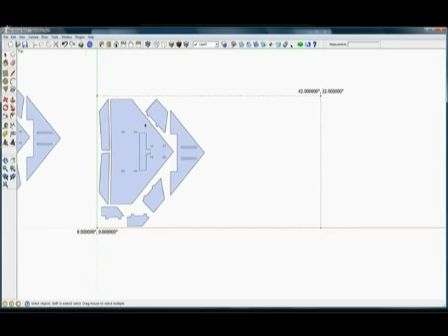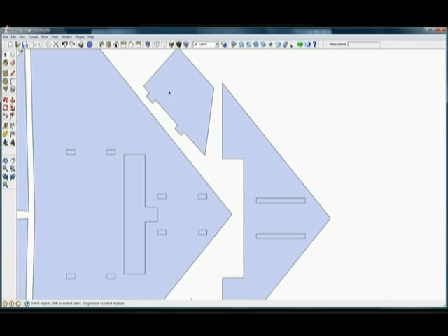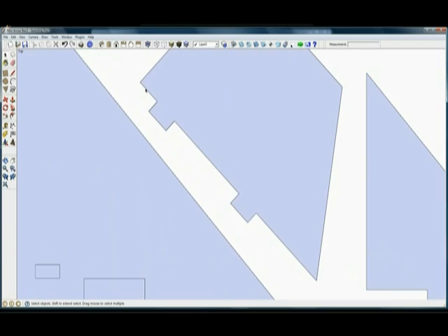But when you're moving parts around, I want to share a couple of things with you. First thing to remember, we have a 1/8 inch bit that it's going to be centered 1/16 off. That's the radius of the bit, so that as it cuts out this part, we can expect that there's going to be a 1/8 inch path away from this part when it gets finished. And then this one is also going to have that same 1/8 inch path that the bit is cutting away.